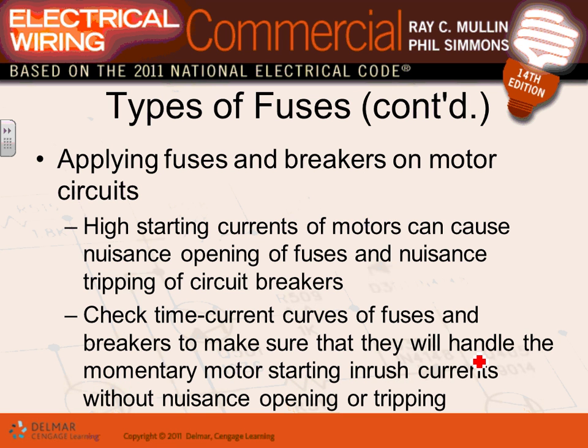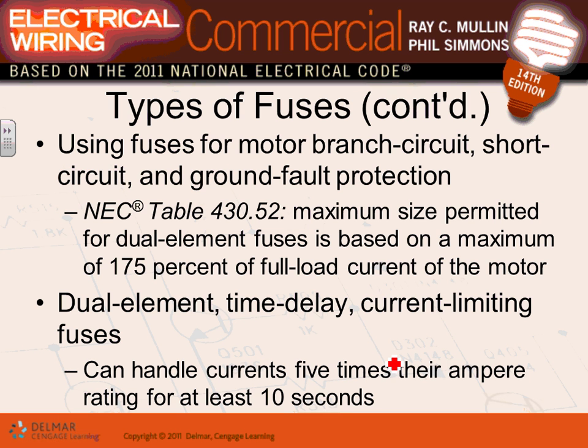Okay, so that type of dual element time delay fuse, guys, will also allow you to operate your motors without tripping on the start. It will handle the inrush current, which is every time you start the motor, there is a current 6 times larger that comes through the system to start the motor. Dual element time delay fuses will handle it better than non-time delay fuses, so they won't trip when you start your motors.